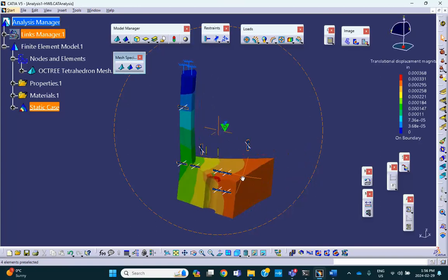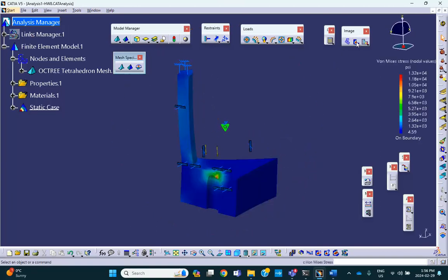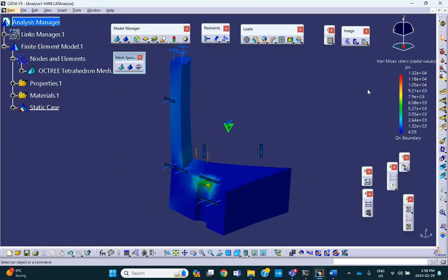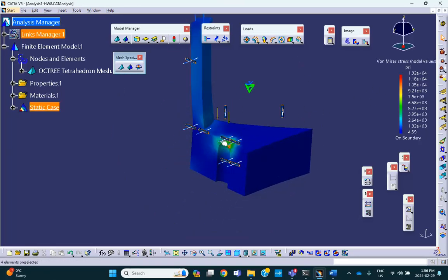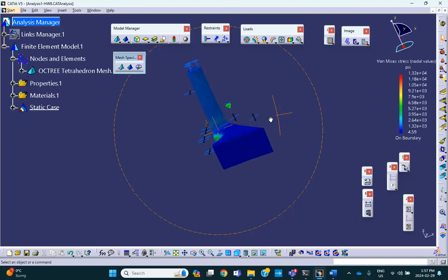And if you want to see the von Mises stress, right there. The way I'm doing it gives you a big stress around the edges. That should not surprise you because how can you put 5,000 pounds on a line? That's why you expect a large stress there. But that large stress is not realistic, because it's just like trying to take a knife and putting the knife there and standing on it, or 5 people standing on it. Anyway, it's easy to generate good looking garbage, but we're not showing you the assessment of the quality of this thing.